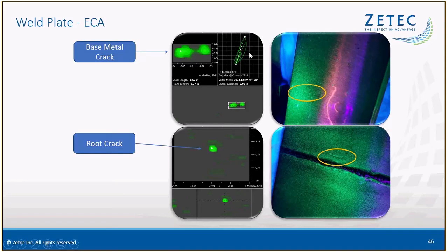You can also take your cursor point in eddy current array and have an impedance view, or some people call this a lizard view, and you can get voltage and phase information on any particular point in the array. And that's important for people who know how to do sizing, depth sizing, using depth sizing curves.